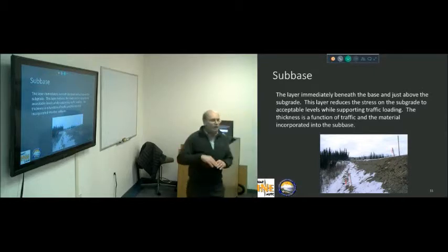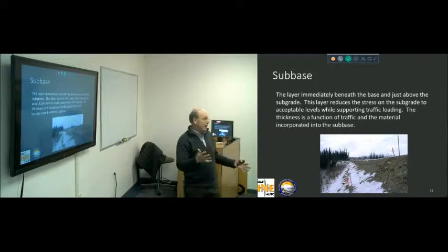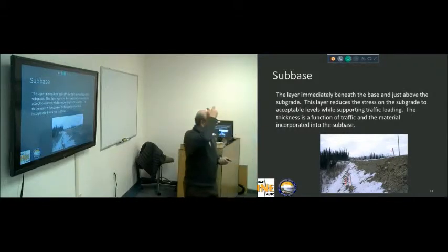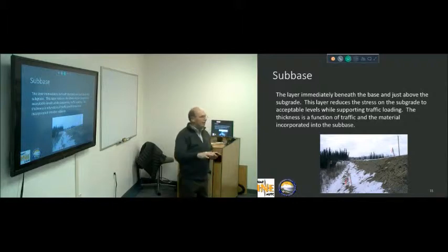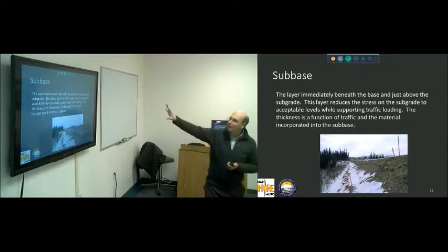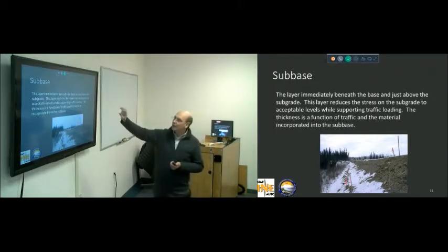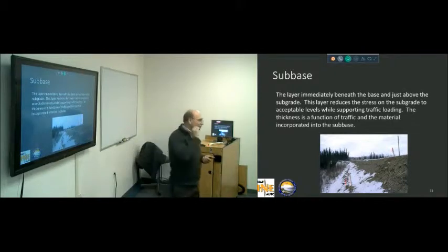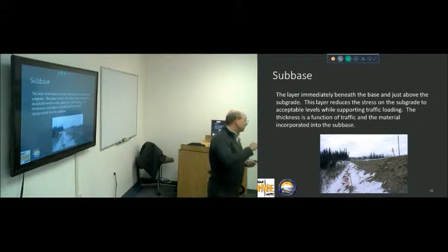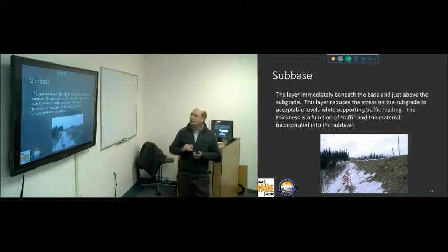But to a pavement engineer, it is any material beneath the pavement structure, which for highways is about 3 to 3.5 feet. So it can be fill material for the purposes of getting grade, but it is not necessarily original ground as the Blue Book would define it. So be a little bit careful. I'm going to use subbase in here. I'm going to use subgrade in this as anything below the bottom of the pavement structure. Okay, so that's a distinction. So keep that in mind as we go through that.